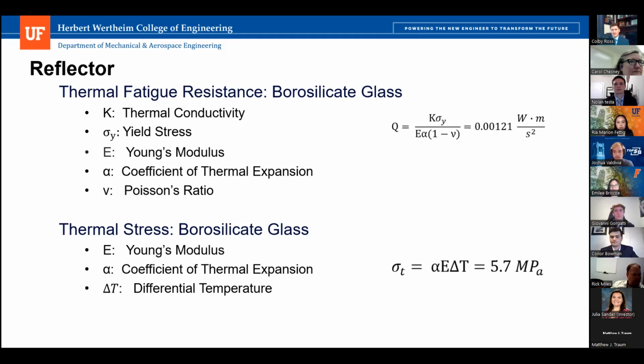The stress wasn't as negated, very minimal compared to the fracture stress, but we really wanted to think through the expansion of all the layers that comprise the reflector. So you've got the glass, the adhesives, and the silicone, and all those are going to be expanding as the temperature rises and falls throughout the day.